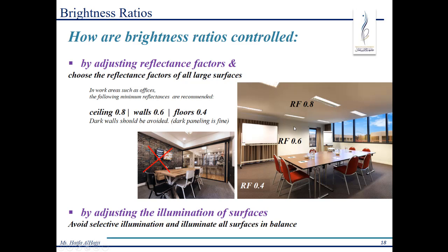If you remember in the first lecture we took on lighting, we said that the reflectance factor ranges between 0 and 1, and it's never 0 and never 1. We have a reflectance factor of a blue object of 0.05, which is 5% reflection, and at the maximum, the reflection of a white wall, for example, is about 85%.